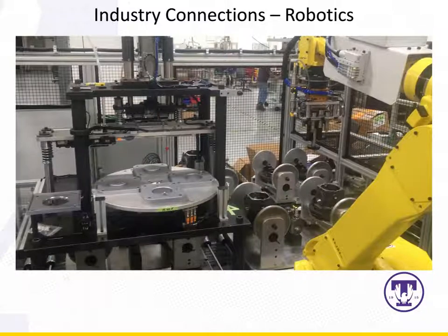Then there are situations where the motion that you need is not easily defined, or you know it's going to be exceptionally complex, like the motion that would be necessary to take a component from an unspecified location on the cart that was over here in this corner. So those were not held in place. So this robot had to use a camera to figure out exactly where it was, to know where to put this tooltip and pick that component up. So there was no way to know ahead of time exactly where this robot was going to need to go. So it'd been very hard to have used some sort of motion that was predefined and locked in to a certain path. So instead, you can use a robot, and that gives you a lot of latitude to be able to figure out what you need to do. So robots are helpful when the motion that is necessary is not easily definable beforehand, or when the motion is going to be necessarily complex and dynamic.